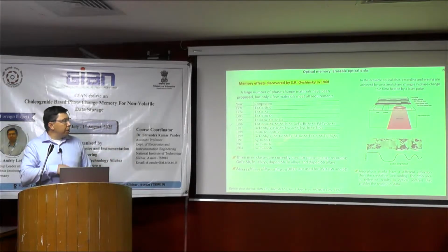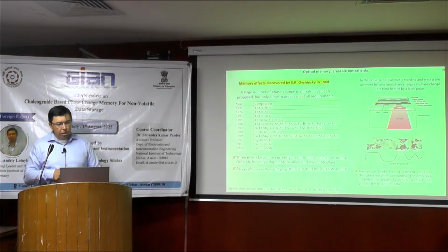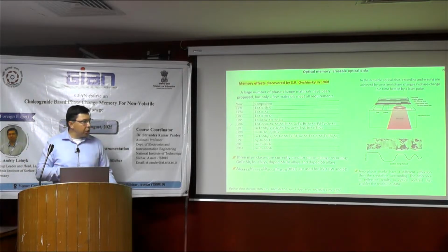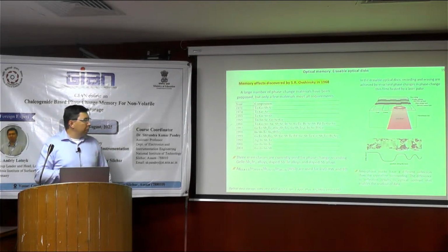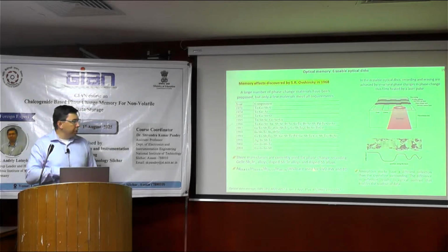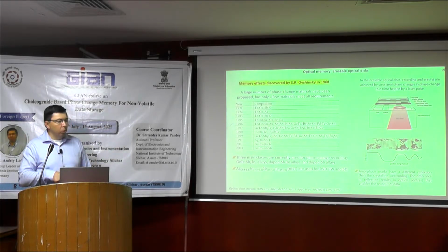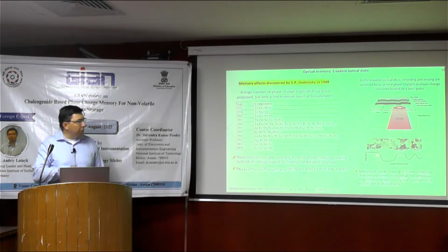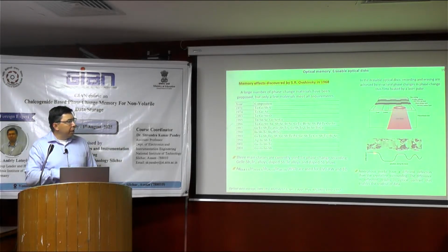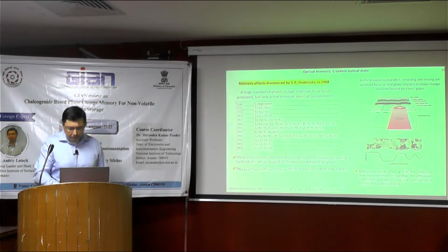So these materials showed these effects, writing and erasing the information based on the crystalline and amorphous marks, and then based on compositions like AIST, the companies developed DVD-RW and Blu-ray discs. Because the crystalline mark has a different reflection than the amorphous mark, you can store the information 0 and 1.